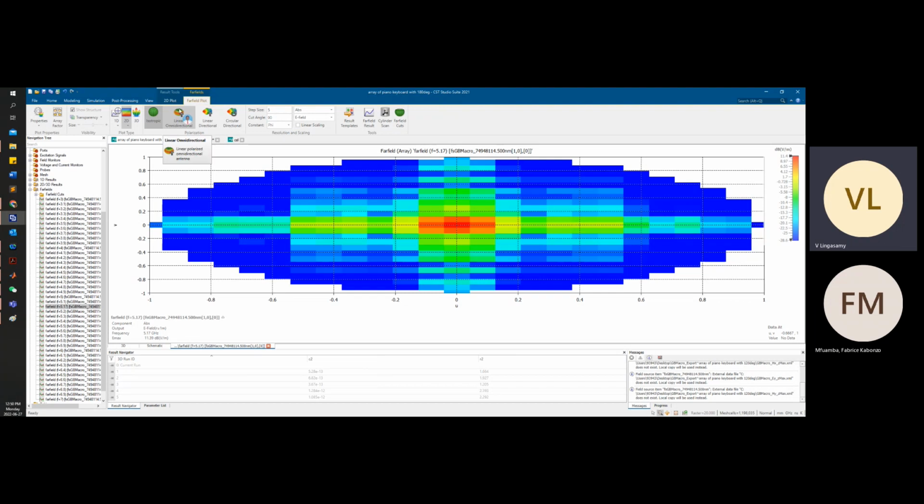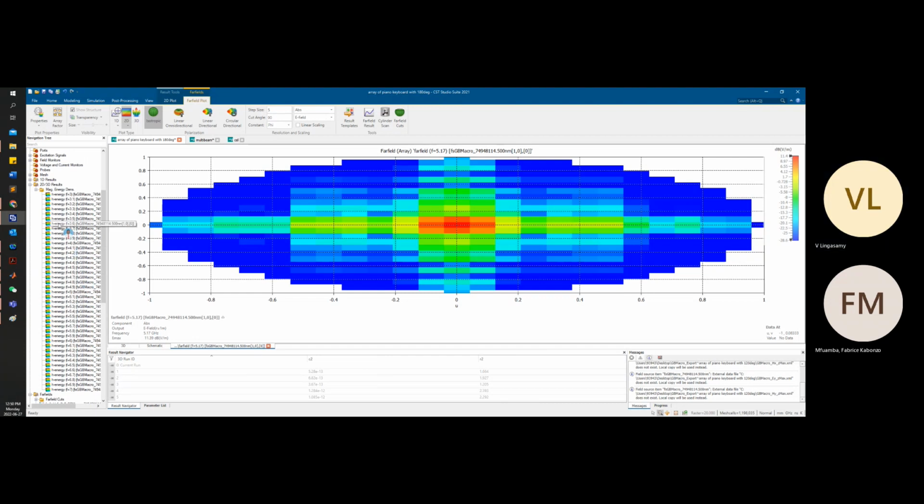Can you go back to where you clicked on this one, the far field pattern, right? No, not this one. Come down, please. Go left. Here, 2D, 3D results. You see, please enable this E field in the field monitor. Then you will see phase and everything, but you have not enabled the field.